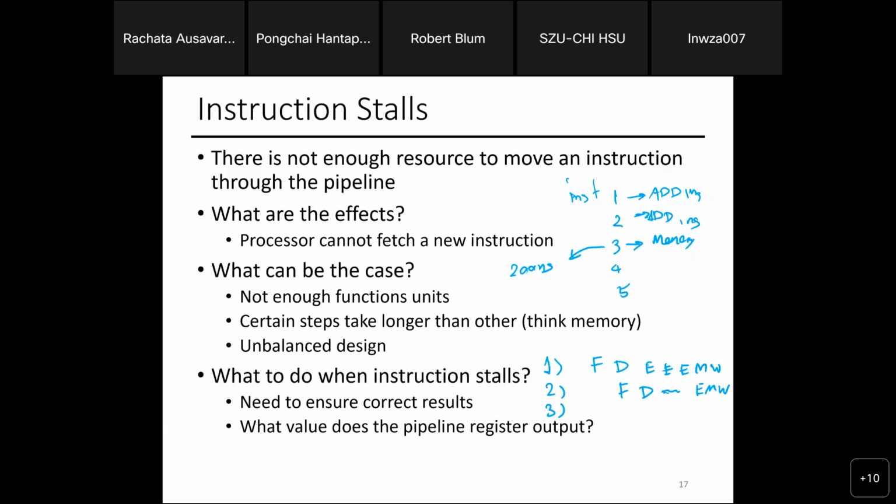Okay, so most of these registers, if not all, will have the write signal going into them. The way you overwrite the old value inside the buffer is you send the write signal, say, write enable. Then the whole thing will get replaced by the input. Otherwise, whatever input goes in, if I don't enable the write signal, it keeps the old one.